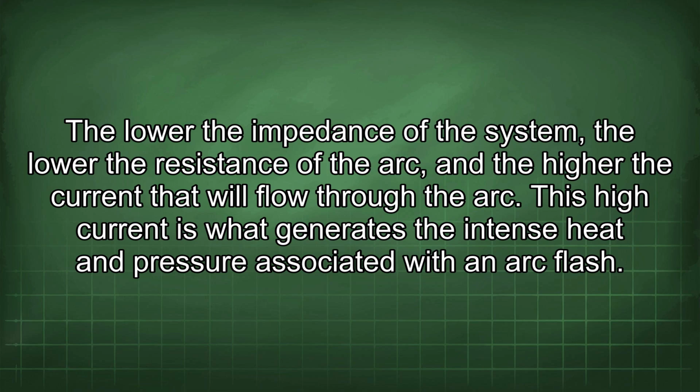The lower the impedance of the system, the lower the resistance of the arc, and the higher the current that will flow through the arc. This high current is what generates the intense heat and pressure associated with an arc flash.